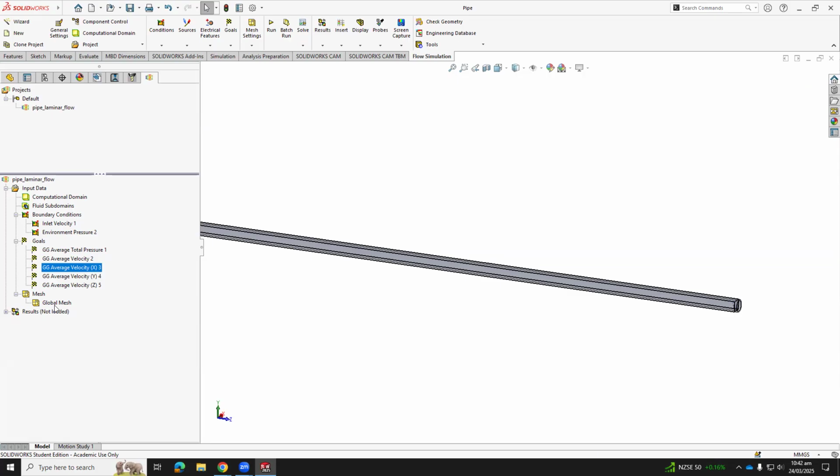Global mesh. Meshing in CFD is easier than anything. Why do you reckon that is? It's easier than the FEA analysis. You never get issues with meshing in CFD like FEA, because the CFD will mesh the box, the computational domain, that cube, and always mesh it as a nice geometry, not going around. And inside is the fluid.